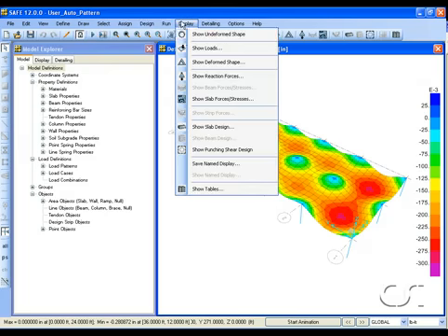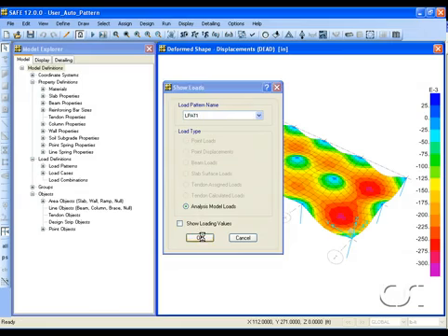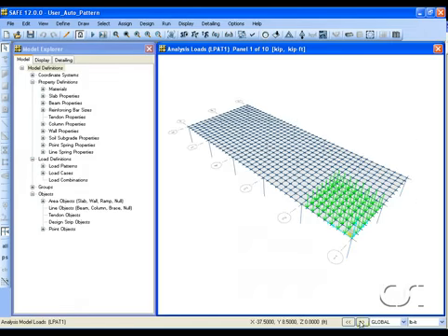Go to the loads display and select the pattern live load. Again, the program has applied live load to individual panels based on the grid layout and calculated results based on the multi-step process. Results from each panel are combined in the single LPAT1 load case.